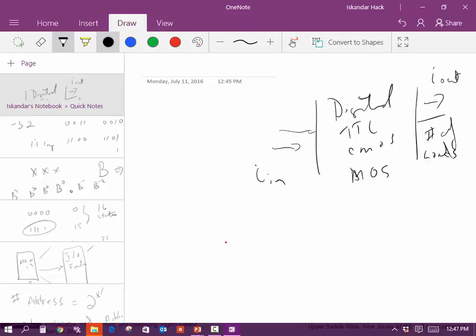Now, if you take, for example, a pin such as AD0, it could be tied to 20 different loads. And when I say 20 different loads, every memory device, every address decoder is going to be tied to this bus. So when we tie a lot of things to the bus, we have to put buffers on there in order to ensure that we don't draw too much current coming out. And we also have to look at what's going into this, because that's a certain amount of current.